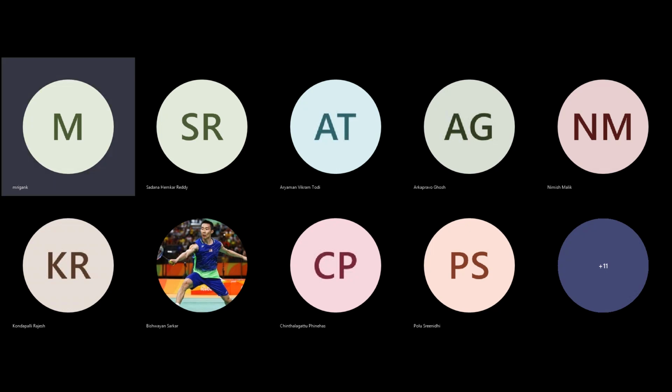Likewise, in certain low noise amplifiers, the front-end amplifiers, you are forced to keep the area large to minimize the effect of noise, increasing the W times L area of the device. We have studied this in the noise analysis, right? If you have to reduce the thermal noise, you have to increase the GM of the input device. If you have to reduce the flicker noise, you have to increase the W into L of the input device. So that will also impose its own constraints. In those cases, you may have to keep several hundreds of micro also. That is possible. So it depends upon the requirement.